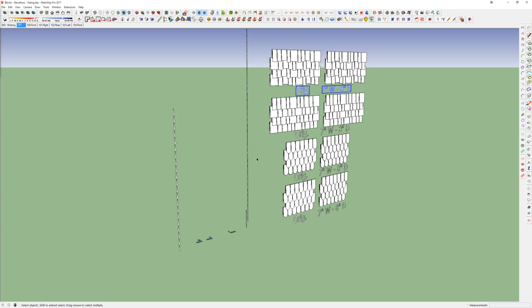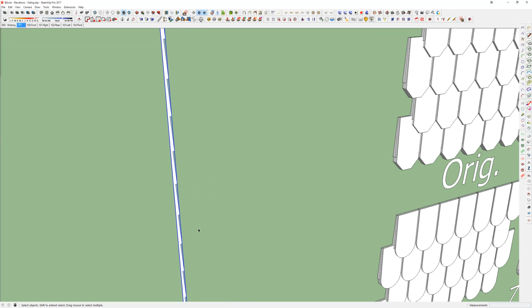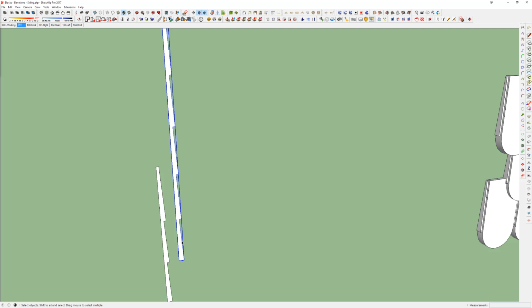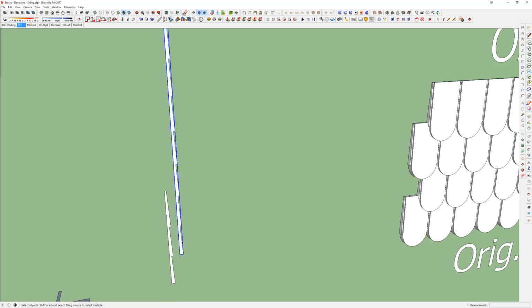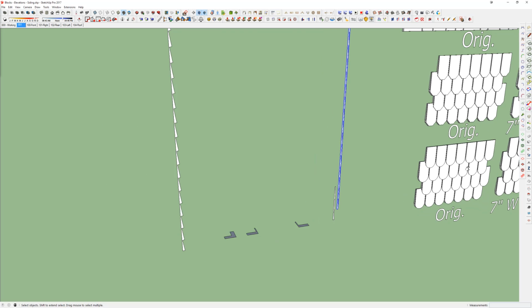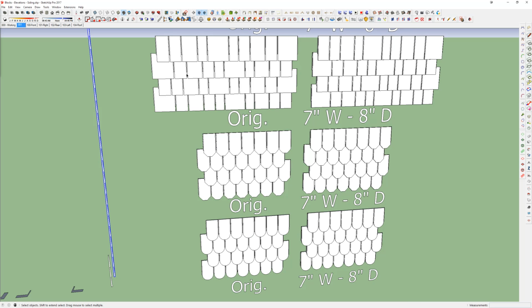For the most part, we're really going to use this right here, which is just a profile of siding that was actually made from a CAD file of actually built siding. So it's fairly accurate, and as you can imagine, we're going to use this with a push, pull, and or follow me command. But I also have these over here if you ever need to do more shingle style kind of stuff. And we'll talk a little bit about this towards the end.